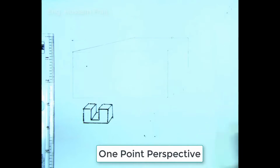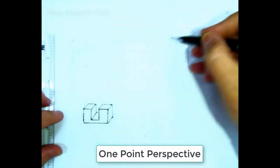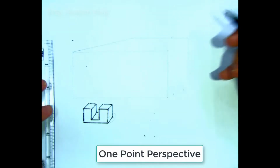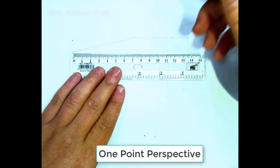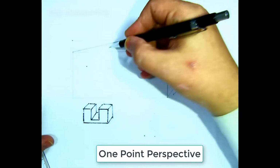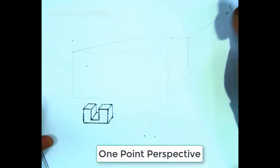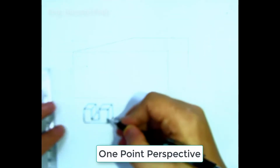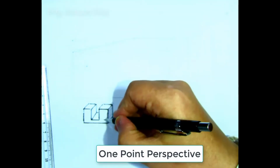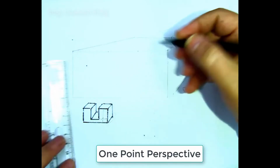I want to draw this object using one-point perspective. Okay, for one-point perspective you only have to take care of depth, because the width and the height remain parallel. Okay, so choose like this. This is from 1 to 11 like this. Choose any 2 points here, but you have to keep in mind to make this line and this segment equal. Okay, and if you notice here, this object, this is not in the middle, it's closer to the bottom of the object. So this line is longer than this line.